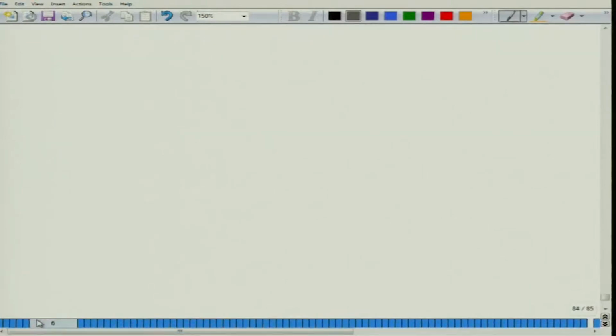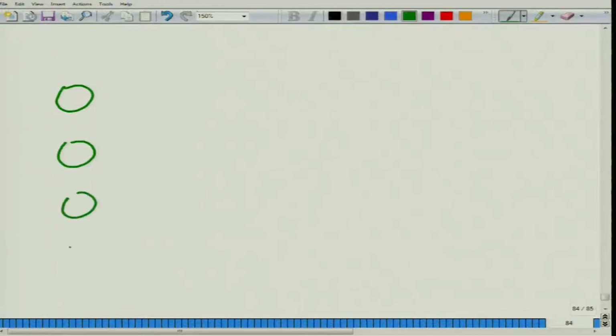So what I have over here is basically the first stage of the trellis. So let me start by drawing the first stage of the trellis diagram. So these are your states 0 0, 1 0, 0 1 and 1 1, and we know at the next time instant we have a similar repetition of the states.